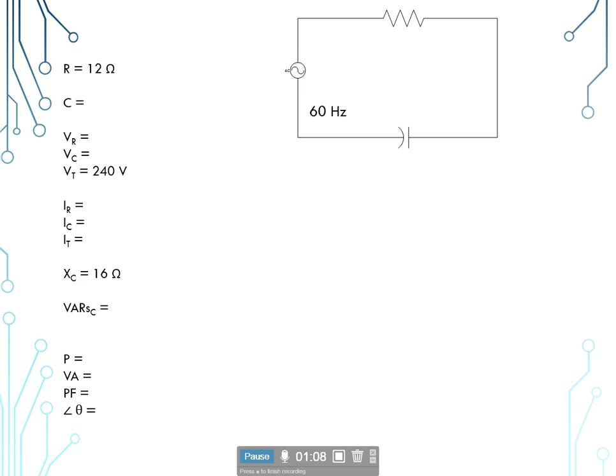With that being said, now the line that runs over the x-axis is always going to be the resistive part of our circuit. The vertical line on the right will always be our reactive part of the circuit, and then the hypotenuse, the longest leg, will always be our total. Now we can use this part of the Pythagorean theorem. We can use this with our current, with our voltage, with our resistances, or our ohms on here. Now, whatever we make the value for one side, the other two sides have to be of the same value for this to work.